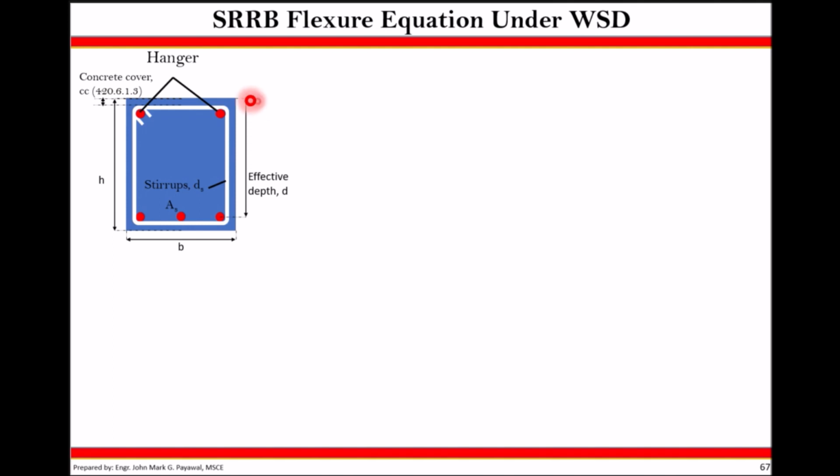So it can be checked on 420.6.1.3 of the latest NSCP. So you can see there your beams, your girders, your columns, which use also 40, your slabs or walls using at least 20 millimeters, and footings or foundations at 75.